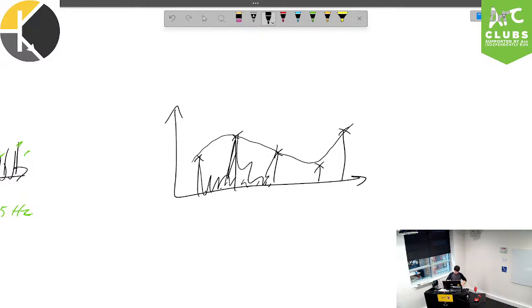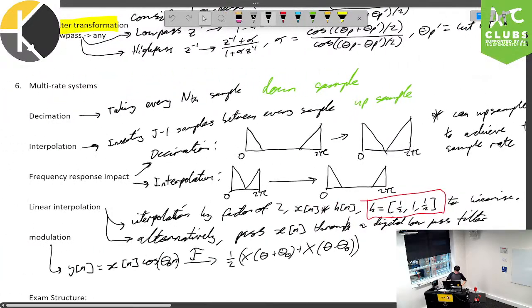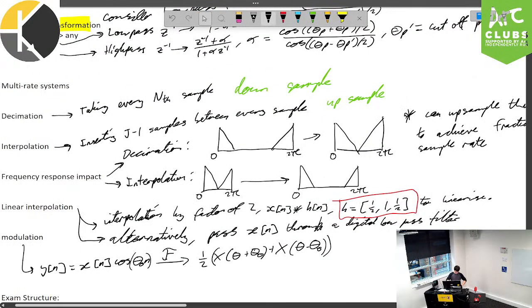So by applying this manner of understanding to a newly interpolated sampling, we can go ahead, erase whatever high-frequency noise stuff it believes is bringing it back down to 0, and only keep what would make it smooth, okay? And so that is called a low-pass filter interpolation.